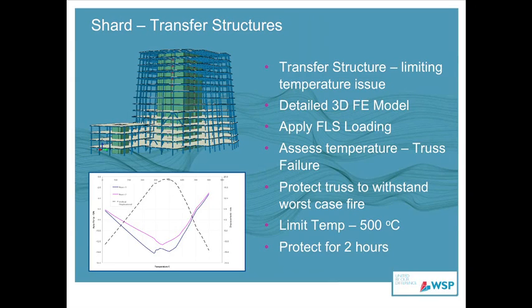And this is because, in some ways, the compressive load in those members is not constant. If we have one member that's heated and one that isn't, the one that isn't heated actually provides a great deal of restraint to the one that is being heated. So we have a straightforward restraint to thermal expansion problem. And this can actually be seen in the bottom graph here.